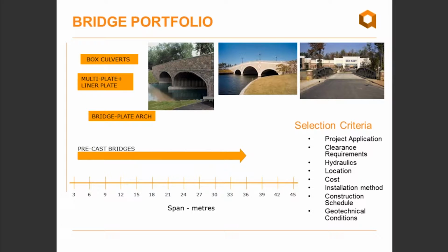Beyond these span ranges, you can also design buried bridges using precast solutions to accommodate up to 32 or 33 meters in clear span. That can be achieved with our segmental precast arch units. The one that Armtec carries is the BEBO arch segments. But today, as I mentioned, we're going to be focusing on the steel options to highlight some of the relatively recent developments in that product group and showcase some of the efficient and cost-effective aspects of buried steel bridges.